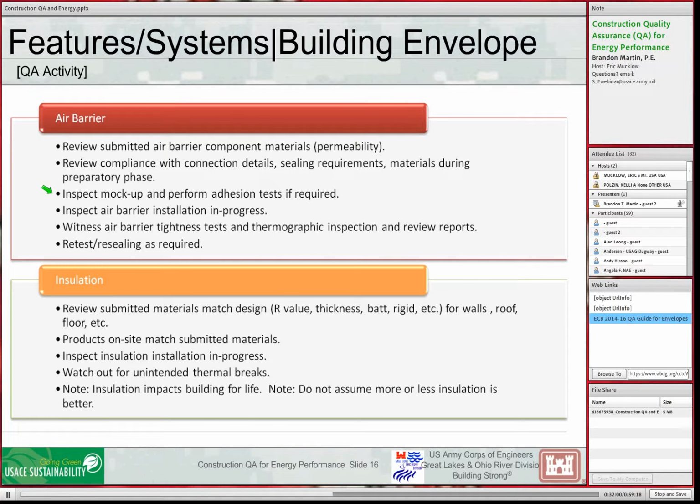If mock-ups are required, we need to make sure that they're performed, built in and tested. We need to witness the air barrier tests. We need to retest and seal as required. I know there was a webinar not long ago on this very topic, so I'd suggest going back to the YouTube site and reviewing that if you need it.